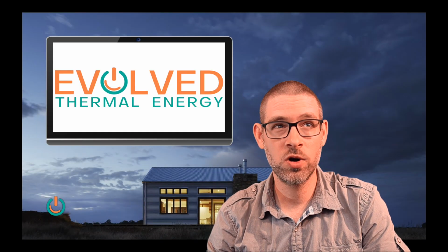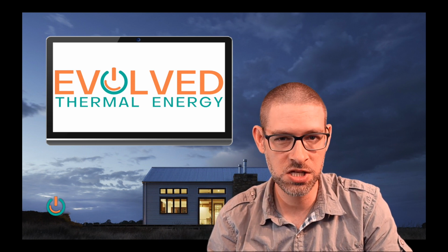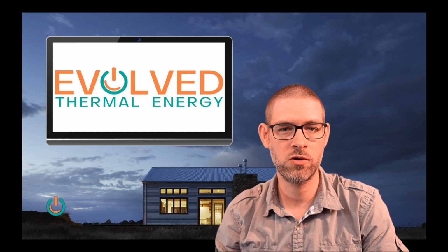What is a kilowatt and what is a kilowatt hour? These two units of measure are often used interchangeably, but they're actually quite different. One of them, kilowatt, is a metric measure for power. Kilowatt hour is a metric measure for energy. If you pay the utility bills at home, specifically the electric bill, you're probably familiar with kilowatt hours. The utility company uses that to measure the amount of electrical energy you've used in a given period of time. But a kilowatt hour doesn't need to be used just for electrical energy.